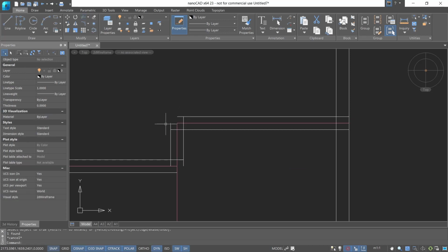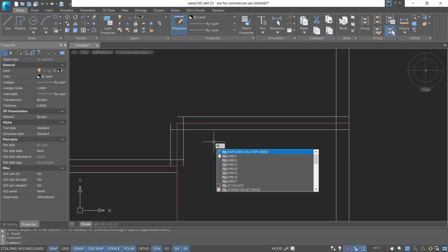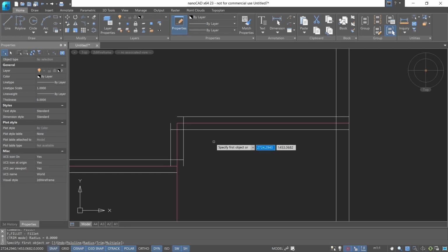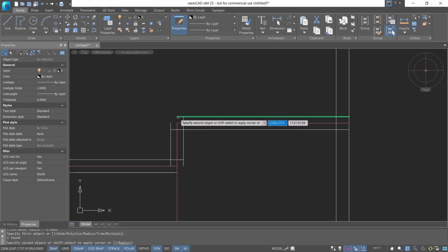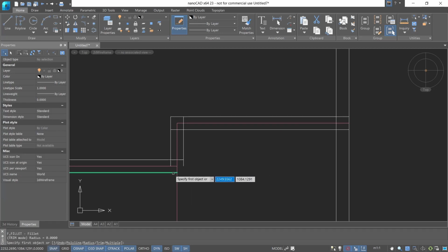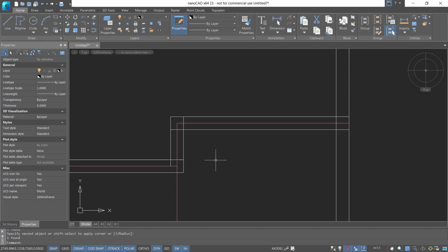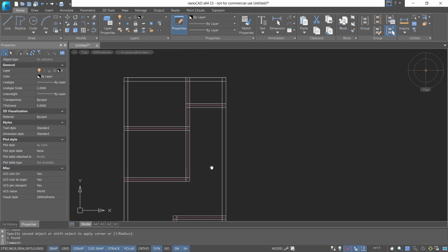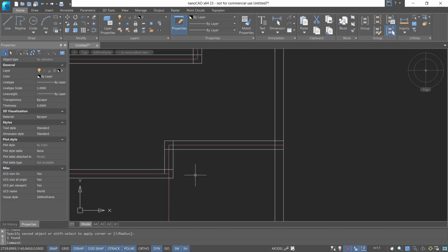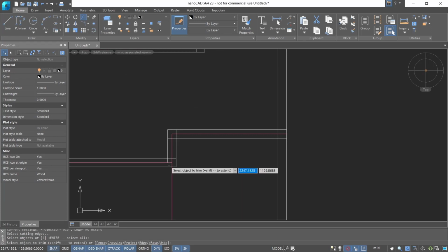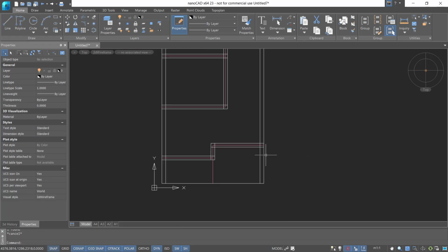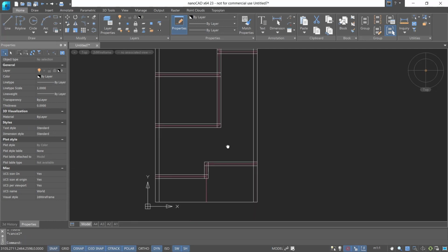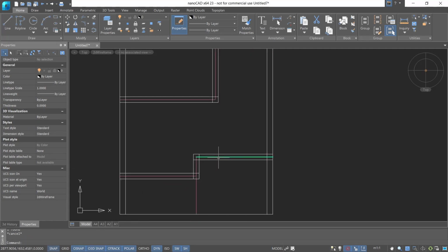Now, to connect these two lines, we can use the fillet command. You can type fillet, press enter, hold the shift button, and then click these two line objects to connect. But again at this point. Next in here. And then for this line, we can extend by using the trim command. Okay, that's it. Now you can hide these center objects by clicking on the layer tools and then checking at this icon to hide.